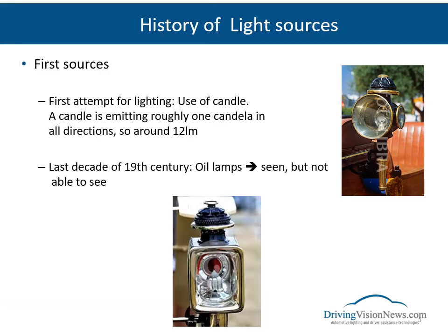At the beginning of automotive, the only possible source was candles, emitting roughly one candela, as this unit was created with this reference. Another important unit for light is the lumen, for the quantity of light. It is defined as the light from a source of one candela and received by a steradian, so by the surface of 1 square meter on a sphere with 1 meter radius. The total surface of this sphere is 4π, so roughly 12. And so a typical candle of 1 candela is emitting 12 lumen, still very weak compared to modern lighting.